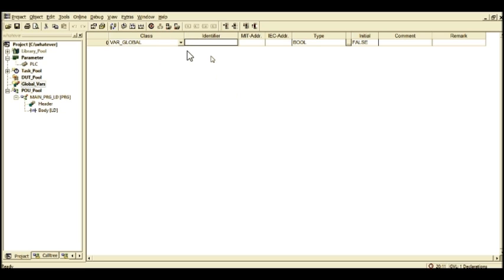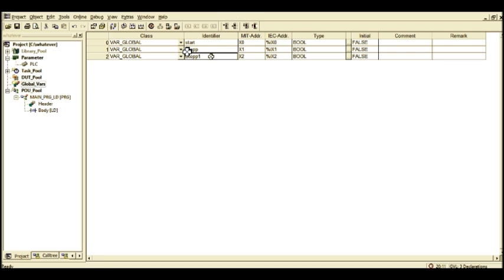We're going to start off with the start function of the PLC, like the button you use to start it with. That one has an input on the PLC which is called X0. I've chosen that, and we now need to make some more variables, as we'll have to do a stop and an emergency stop function as well.